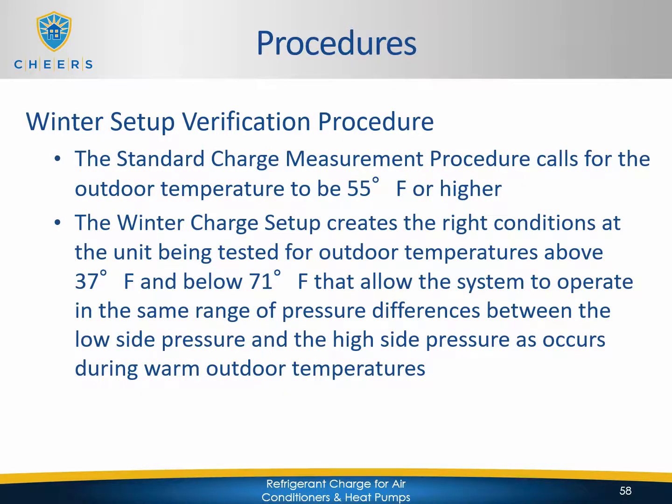So why use the winter setup verification procedure? You see, the standard charge measurement procedure calls for the outdoor temperature to be 55 degrees or higher. The winter charge setup creates the right conditions at the unit being tested for outdoor temperatures above 37 degrees and below 71 degrees that allow the system to operate in the same range of pressure differences between the low side pressure and the high side pressure as occurs during warm outdoor temperatures.